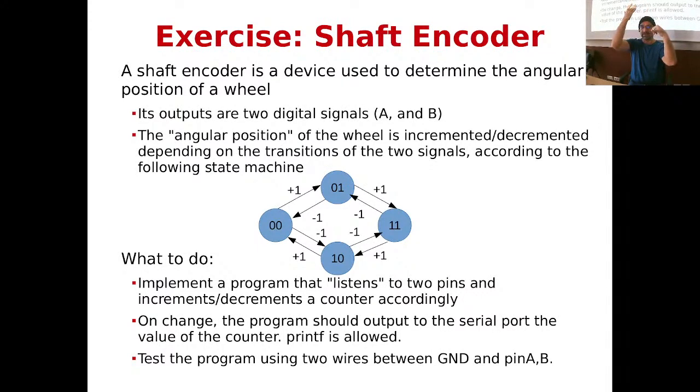If nothing is in between this ray, then you register a 1. Okay? Agreed? Now, what happens if you have an object that moves from left to right? Then you will see 1, 1, because there's nothing in front. Then the object comes from left to right, so you start observing the first obstruction, and then you have 0, 1. Then the object passes entirely and obstructs these 2 channels, and then you have a 0, 0.